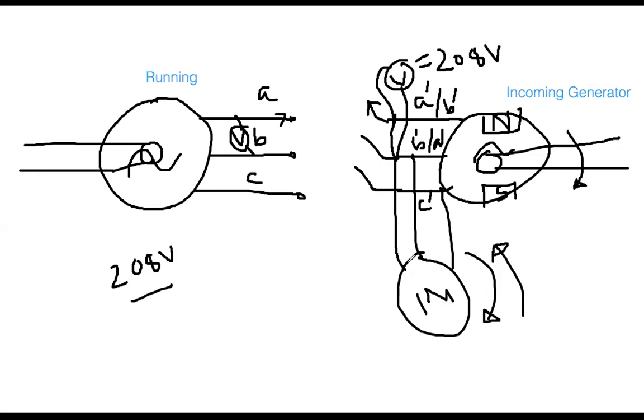That is the meaning. So in the case of the motor, you just swap. You connect A phase here and B phase there. Then you will notice that next time the induction motor runs properly, and the direction is the same as the original for the running generator or existing system. In that way, you can make sure that your phase sequence is okay.